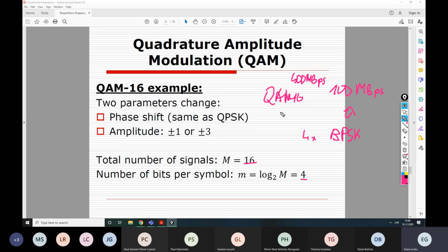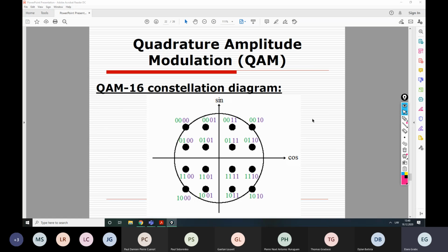Now the drawback, as you know, is lower noise immunity, but if the distance is not large, then we can afford it. And the constellation diagram now is formed as follows. Please note that once again we are limited by this circle with the radius of 1. And this is necessary to calculate correctly the energy. So if you remember, then bit energy divided by noise spectral density was SNR, and we needed this noise spectral density to calculate correctly sigma in order to generate noise with RAND-N function.